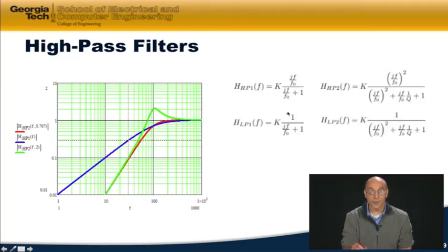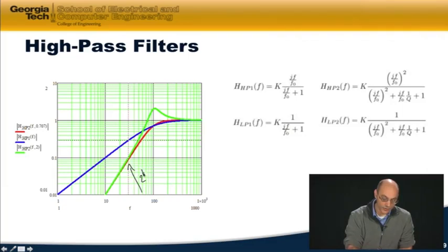Whereas for the low-pass filter, the numerator was equal to the lowest order term in the denominator. And similarly, for the first-order filters, you form a first-order high-pass filter by moving the highest order term in the denominator to the numerator, and you form a low-pass filter by moving the lowest order term in the denominator to the numerator. So to visually see the behavior of these high-pass filters, I've plotted 3 Bode magnitude plots on this graph: 2 second-order high-pass filter transfer functions and 1 first-order for comparison.